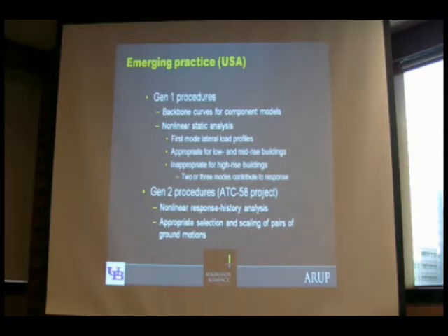And this is an approach that's appropriate for low and medium rise buildings where one mode of response controls the behaviour of the building, but it's inappropriate for tall buildings where 2 or 3 modes in each direction might contribute to the response. Importantly, as we introduced nonlinear static analysis to the United States in the mid-1990s, we recognised these limitations.